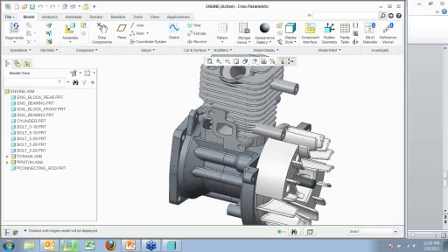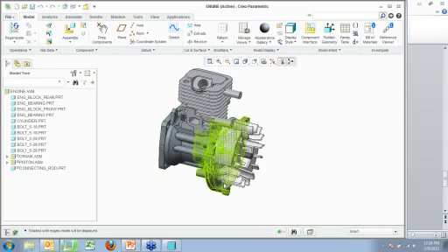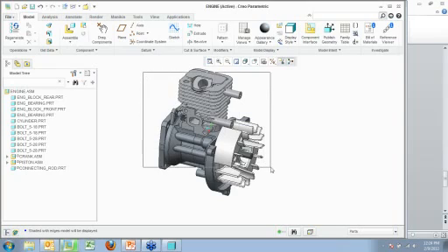So another thing that they've done is, if I want to select parts, they have a new selection feature where I can select things by a window. If you notice, it only selected part of those parts. If you drag from the left to the right, top left to bottom right, or also bottom left to top right, it only selects the items that fall 100% within that box.